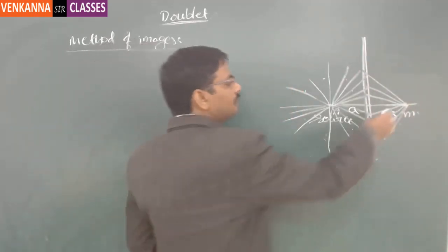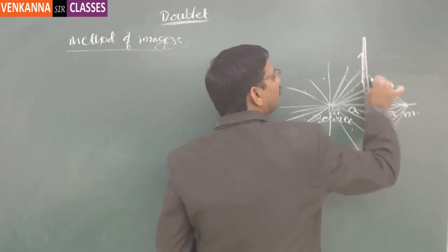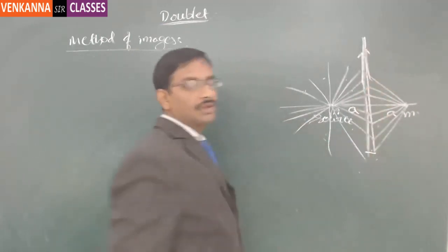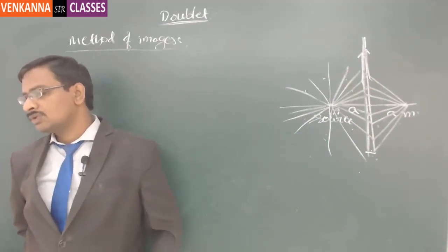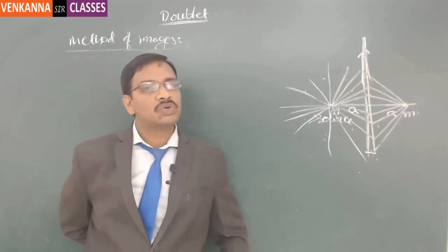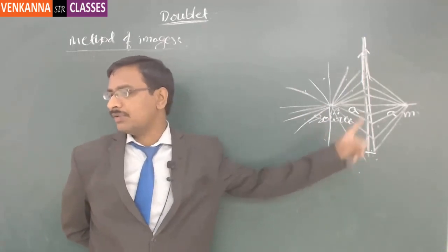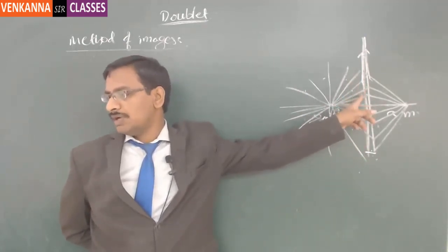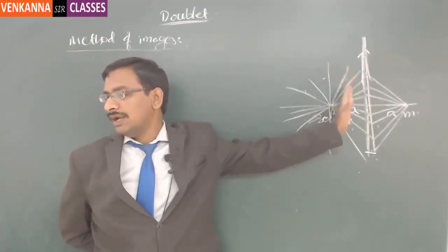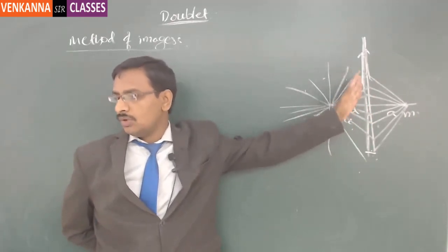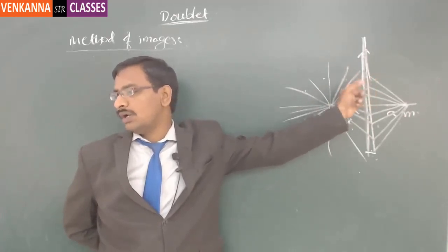Now here, because of this source and this source, these two together will make the flow exactly tangential to the surface of the wall. Correct or not? So by introducing one more source on the other side, these two together will assure the streamline's direction on the wall of the dam. Got it? So on the wall of the dam, the flow is tangential to the surface, so there won't be any flow perpendicular to this surface. That means the fluid cannot cross this wall at any instant, right?